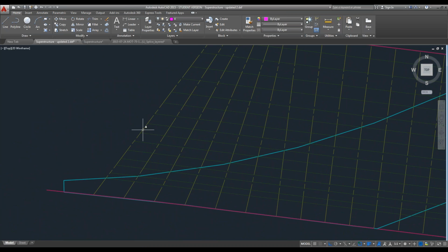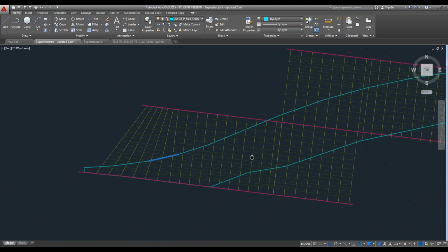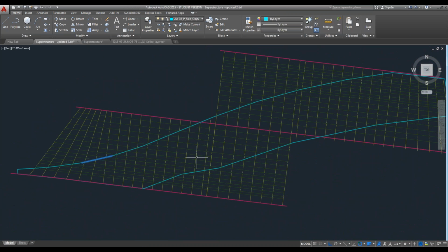And this girder is kept as it was originally. And this girder, the deck outline portion is drawn again freshly using the line element as mentioned before. And one thing that I added in addition to what was already in the drawing is these transverse beams. So in the grillage modeling approach, you actually need transverse dummy beams.